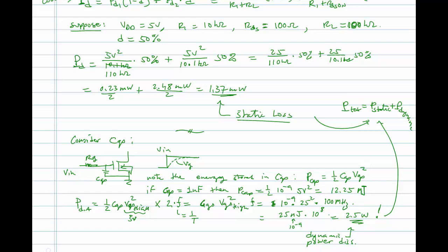So these are just some things you can be thinking about when you think in the context of, what limits a processor from clocking faster than it does. And at some level, it really involves things like we're talking about here, where essentially clocking it faster will dissipate more energy internally in the IC because of charging and discharging capacitors, and that in turn could become a failure mechanism because of over stress thermally. So anyway, that's a little more information on calculating basic static and dynamic power dissipation for an NMOS inverter.